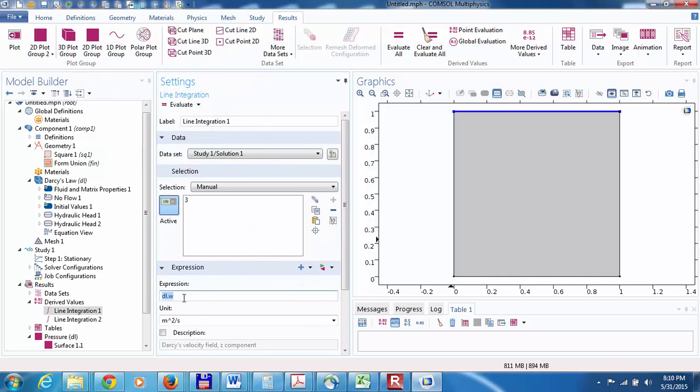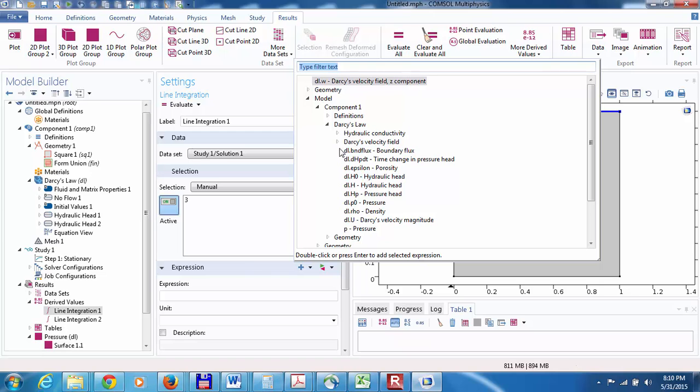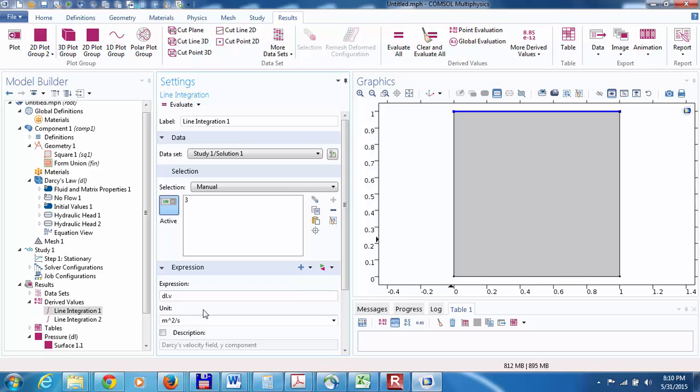Okay, the problem is that I chose the wrong flux, because this is a two-dimensional problem, so we don't have a z direction flux. We have an x and a y direction flux, and we're looking at the flux in the y direction. So for the top surface, this is the velocity. We'd need to multiply that number times 1,000, to give you 0.262 kilograms per meter per second.